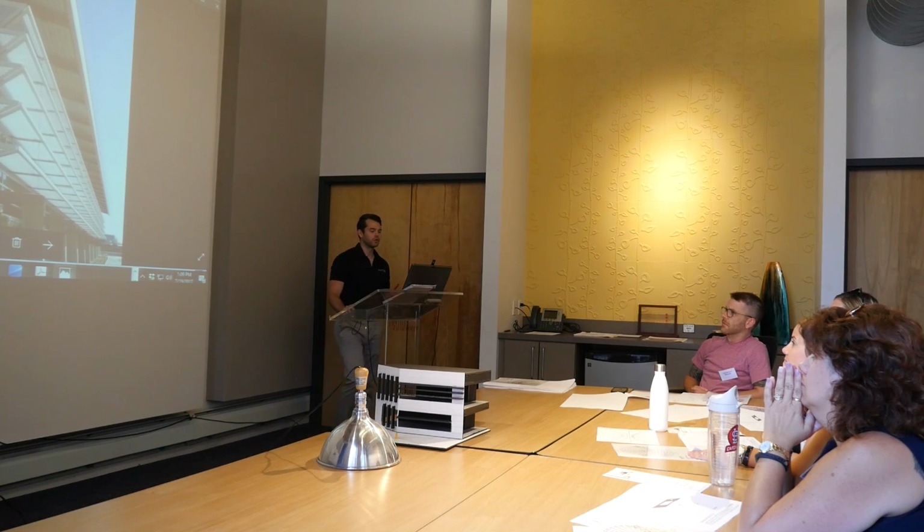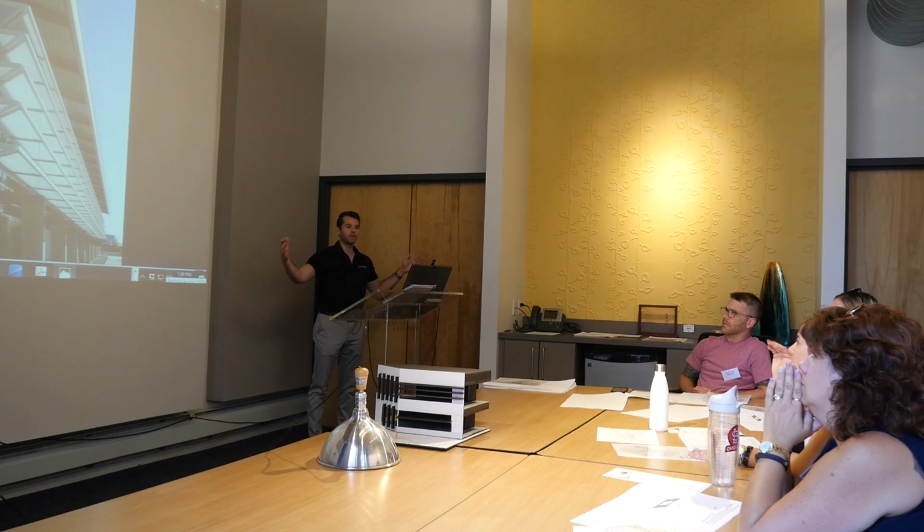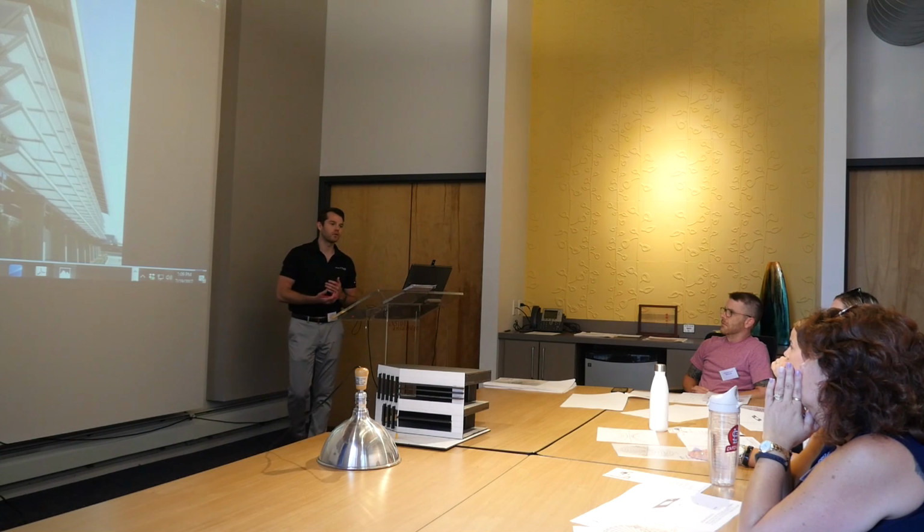They're horizontal louvers, and in using that basic exercise we just did, we can find out how wide the louvers should be, how they should be spaced, and what times of year different parts of the building should be shaded. And then we use that to design the HVAC systems and the energy load on the building, essentially.